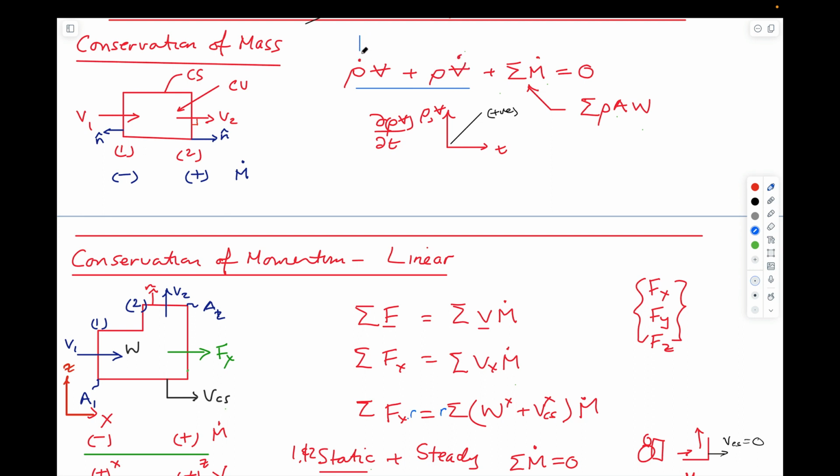We've explained these components, that this represents a tire which is being inflated, where the volume of the tire remains constant, but the density of the gas that's going into it has to change. We've talked about this term being filling a bucket, where the density of the fluid that's going into it, say water, remains constant with time, but the volume changes as it fills up. And so these are the components of accumulation, and those have to be balanced with mass rate in equals mass rate out. And so we do that in terms of a sign convention.